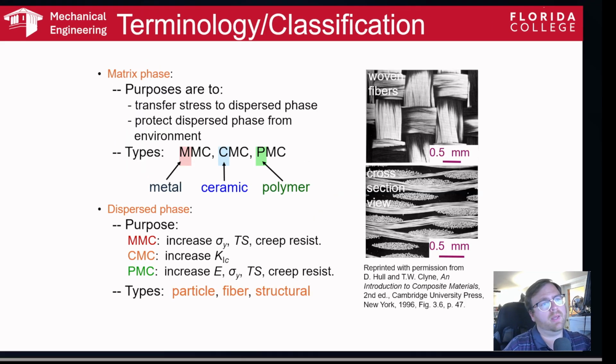Okay, so here on the right, this would be more like, in my opinion, the ceramic fiber, ceramic matrix composites that I worked with looked just like this. So that might be what these are. What you see here is they've actually woven the fibers together to create quite literally a fabric, and then they glue that fabric together with a matrix material. In my case, these were silicon carbide fibers of high purity that were glued together using a silicon carbide matrix of very low purity. So you can actually save a little bit on cost when it comes to strength.